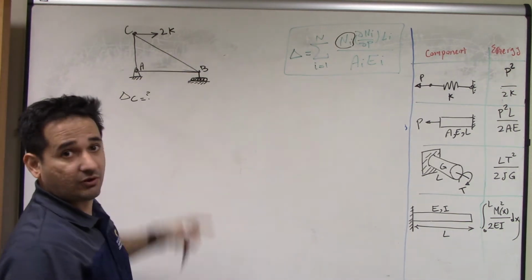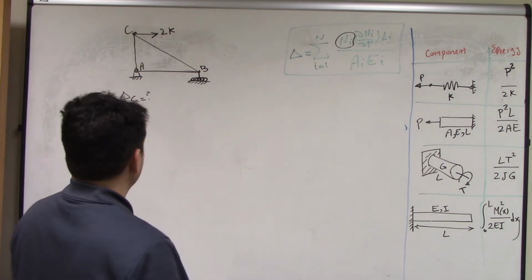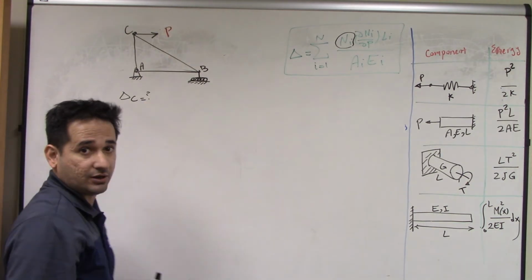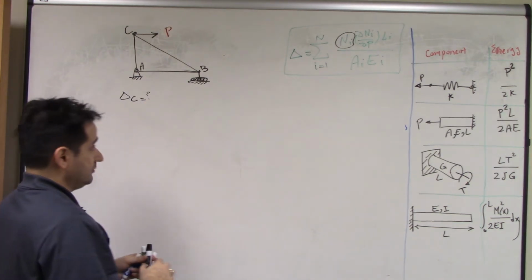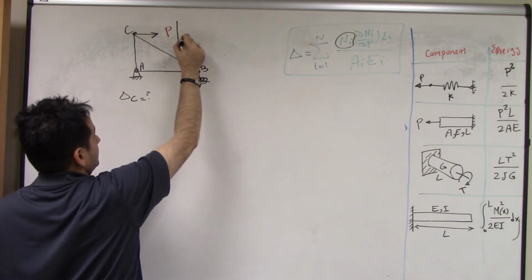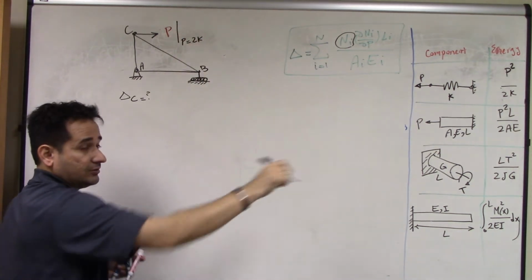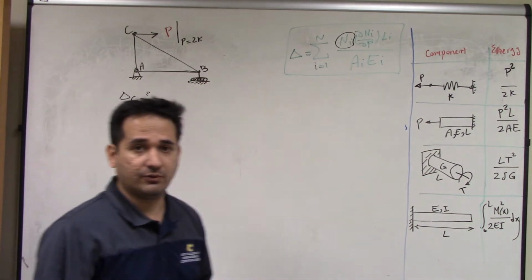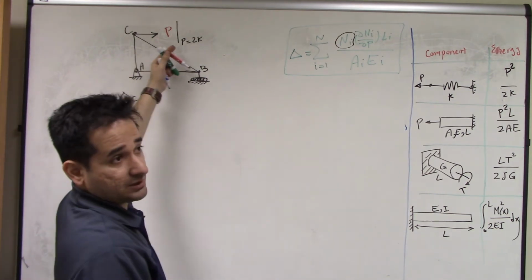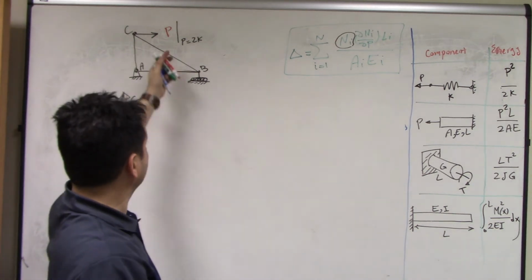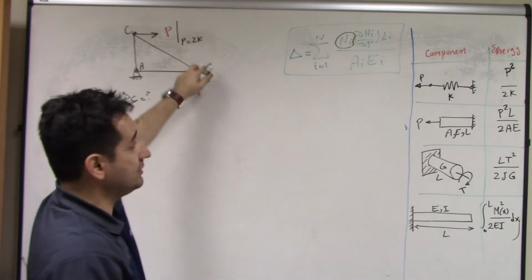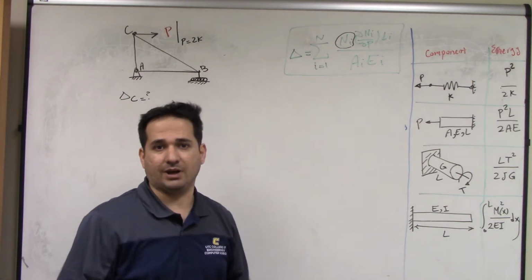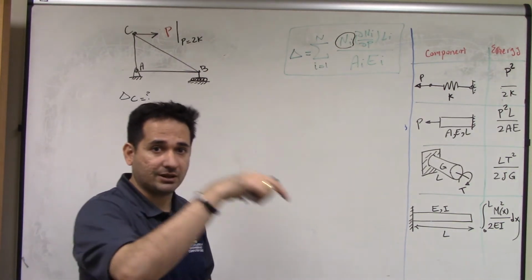Now the question is, where should I apply my P? This is not a P, it's just a constant load. Well, I can have a variable P there, and at the end, when I want to do the evaluation, I evaluate P equal to 2K, for my answer. So the trick here is we make a variable force there. If the force was 0 at some other point where you want to find deflection, then we say P is 0 at the end, when we do all the calculation.